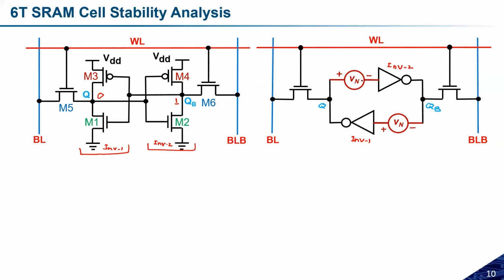The bit cell stability during active operations means read and write. These 2 are the active operations, and the hold operation is not active, because during the hold we are not performing any operation, we are just holding the data.